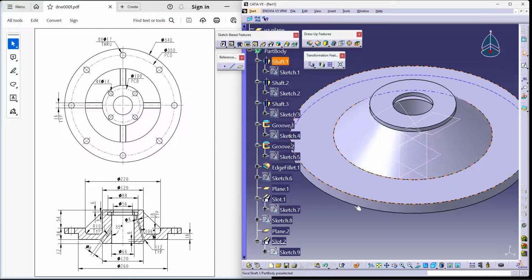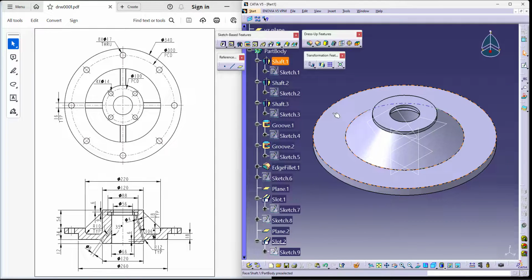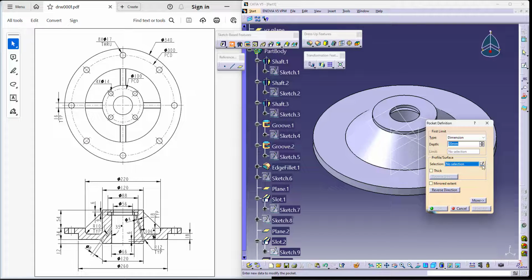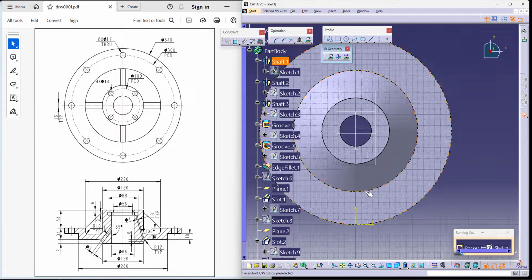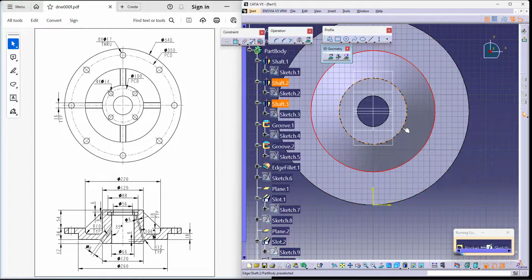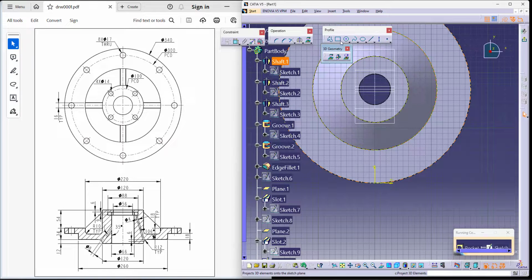Now, since you have understood this, of course, it's easy to remove this shape as well. So let me try to take this space and use pocket, which is easier for us to create a cut using this as my reference and this as my reference. I'd like to remove the material now. There is one sketch here and mirror the same thing onto the other side with respect to the center plane. Maintain and close them, of course. I'll use the center to close them.